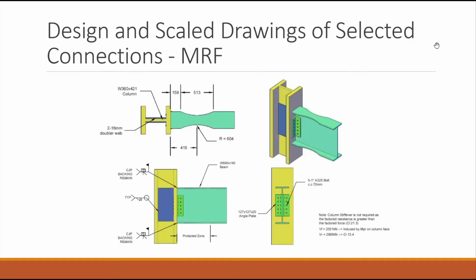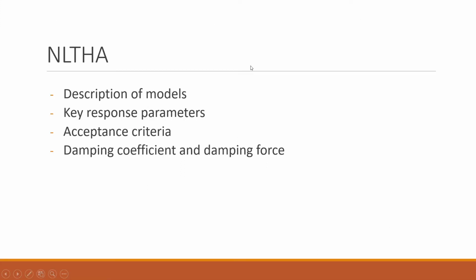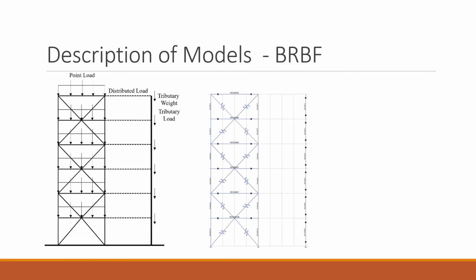And these are the design drawings of MRF beam to column connections. Bolted connection was used here. So now we're going to talk about nonlinear time history analysis. For nonlinear time history analysis of BRBF, the model is simplified to be a 2D model with a single BRBF.